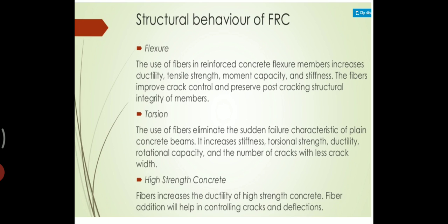Then let us see some structural behavior of fiber reinforced concrete. So first let us see the flexure. In the flexure, the use of fibers in reinforced concrete flexural members increases ductility, tensile strength, moment capacity and stiffness. The fibers improve crack control and preserve post cracking structural integrity of members.